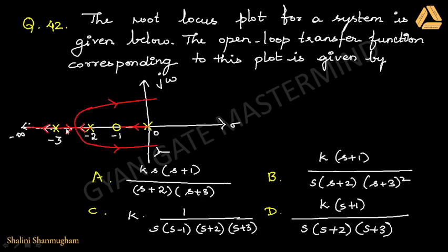On seeing the root locus, you can find there are 3 poles, but actually the root locus starts from this pole and ends at the finite zero because there is only 1 zero here, and the remaining 2 poles start from their respective places and go to the infinite zeros. So this one goes like this and this one goes like this. They meet at infinite zeros.